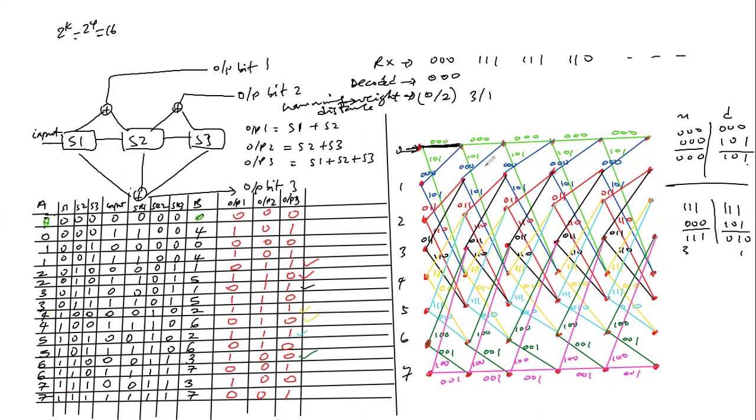The shortest distance is coming downward. So it means that the code that was transmitted is supposed to be 101. So this was received in error. So we now want to trace downward onto this point. So the coded code word here is 101.